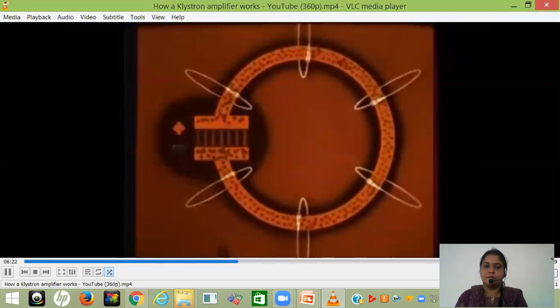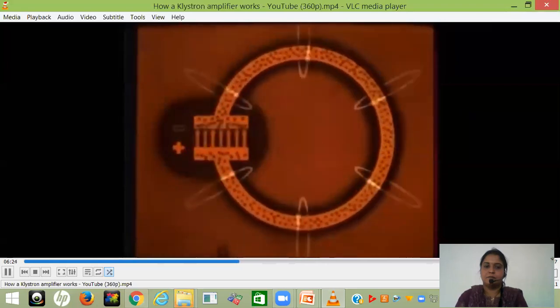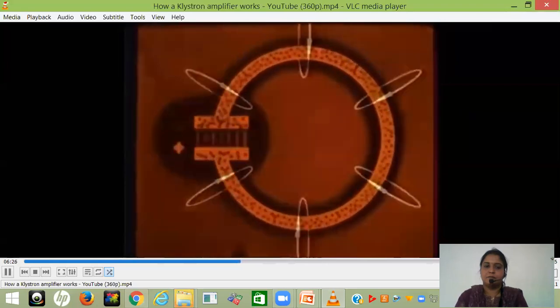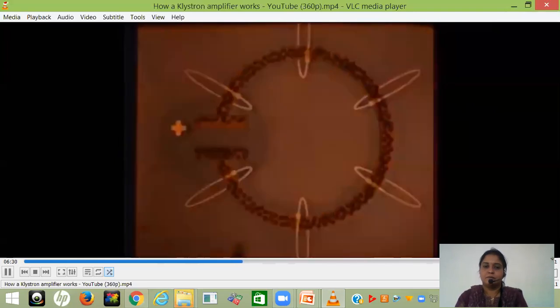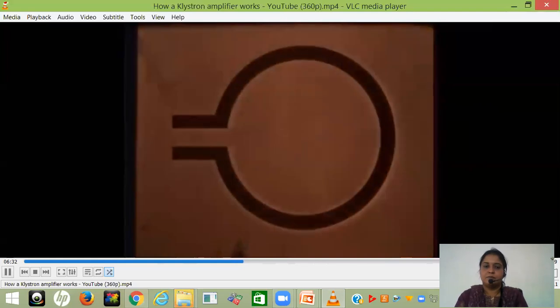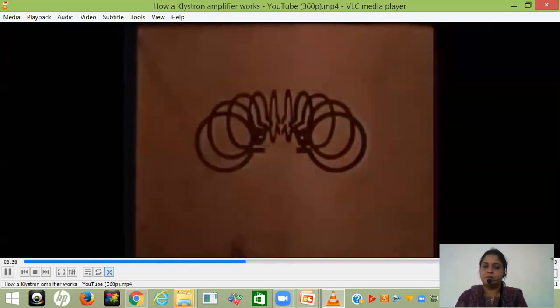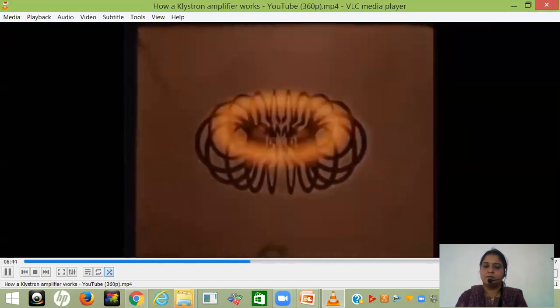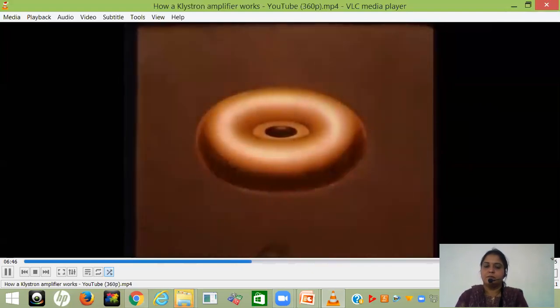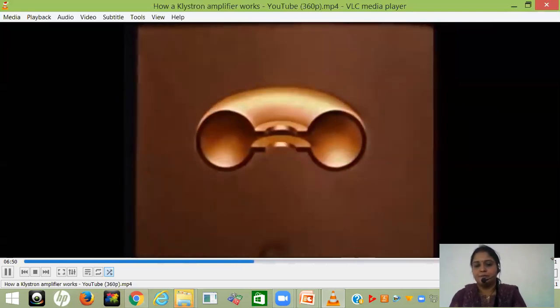With this simple circuit, a rather high frequency can be obtained, because the inductance of a single loop is very small. To obtain higher frequencies still, the inductance can be further reduced by placing two or more loops in parallel. This results finally in the formation of a closed resonator having certain very high resonant frequencies, which are determined by the dimensions and shape of the cavity.